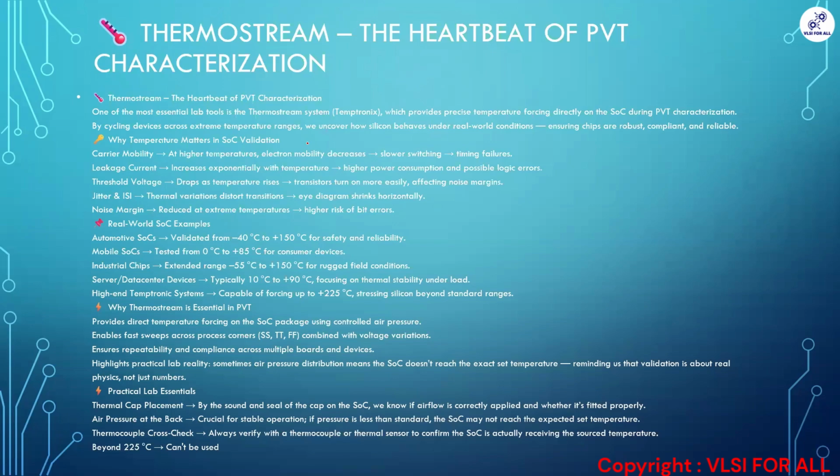For mobile SOC, we will be testing from 0 degrees to 85. For industrial chips, we'll use from -55 to 150. And for sensor or data center devices, it will be 10 to 90 degrees Celsius. And high-end Temptronics systems also have some limits. Beyond 225, we can't source that temperature.